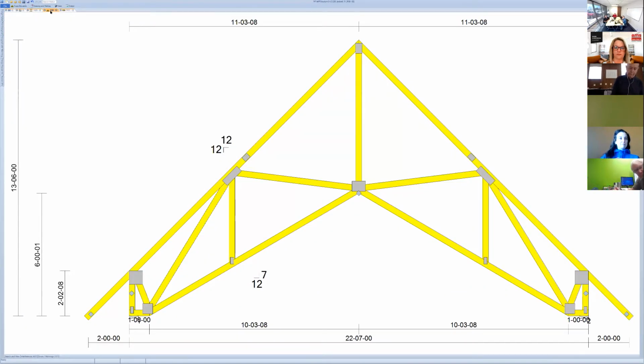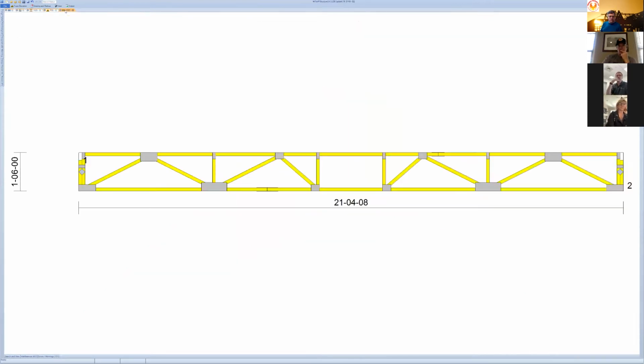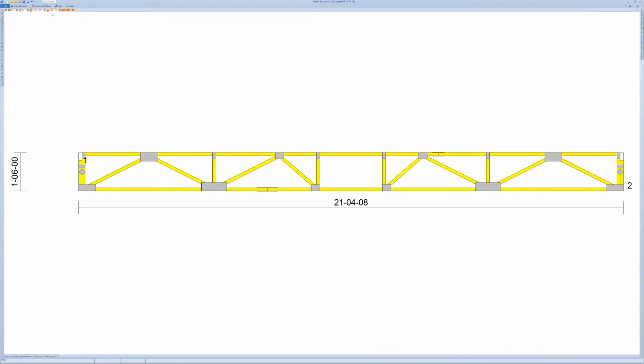We will take the roof truss and superimpose the loads. At that point in time, to keep this truss in equilibrium, it will design the connector plates to the appropriate size. It will also tell us the materials that we need to use within the truss. We use what's called MSR material, which is machine stress rated, and we have values of 1800 to 2400, which means it's the compression rate of the material.